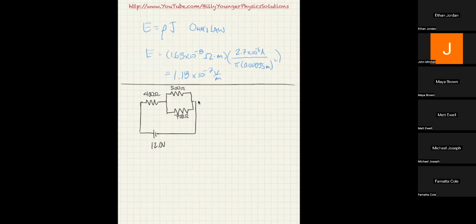What I mean by that is if you're looking at a multimeter, which hopefully y'all have had some experience with in class by now. Your multimeter will have, I always forget which side, but I'm pretty confident this is the 2 ampere side, this one being the 10 amp.